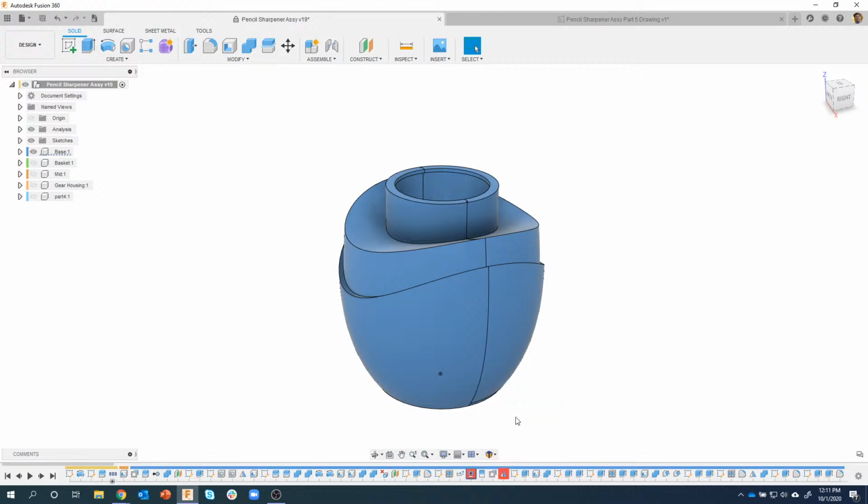And watch what this does. It basically turns off all of these other features. They haven't happened in time yet, and so it's only going to calculate these features if I make a change. It's going to calculate to this marker right here. So this is one of those tips that will really help speed up things, because all I'm really concerned about is what's going on here. I don't care what's going on down here yet. We will, but not right now.